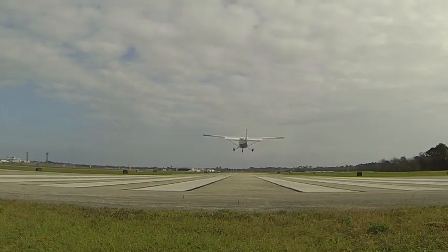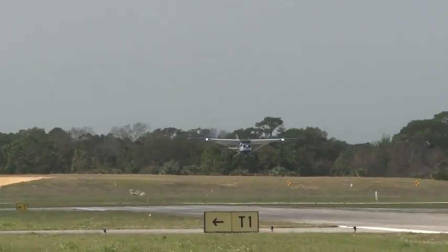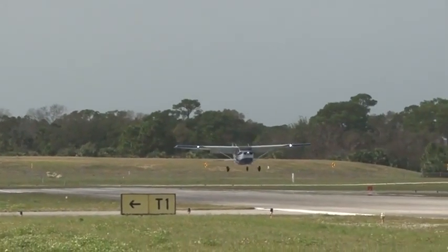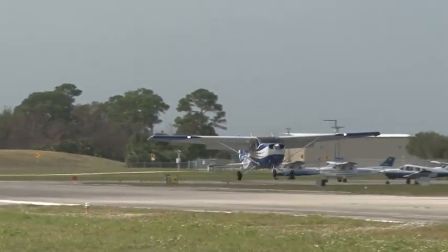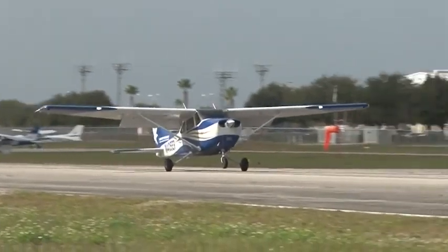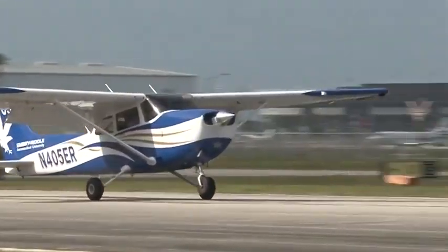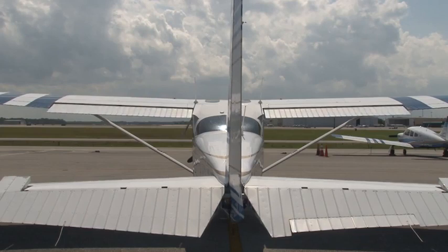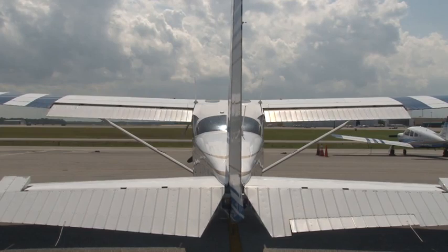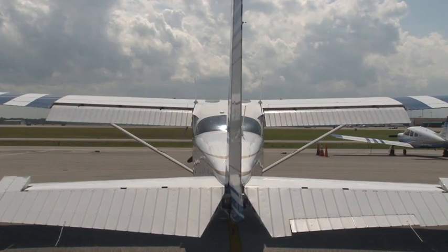We saw how pilots can control the lift generated by the wings by changing the aircraft's speed and angle of attack. However, most airplanes come equipped with one or more additional ways for the pilot to manipulate the wings, and in essence, change the shape of the wings. These are called high-lift devices, the most common of which are trailing edge flaps, or just flaps for short.